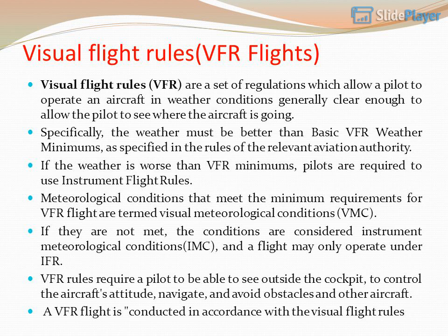Meteorological conditions that meet the minimum requirements for VFR flight are termed Visual Meteorological Conditions, VMC. If they are not met, the conditions are considered Instrument Meteorological Conditions, IMC, and a flight may only operate under IFR. VFR rules require a pilot to be able to see outside the cockpit, to control the aircraft's attitude, navigate, and avoid obstacles and other aircraft.